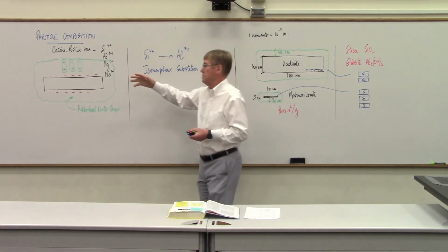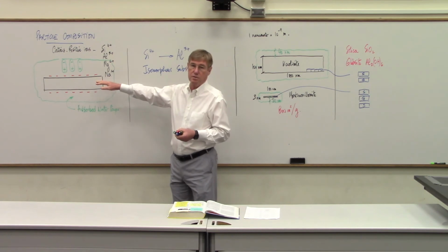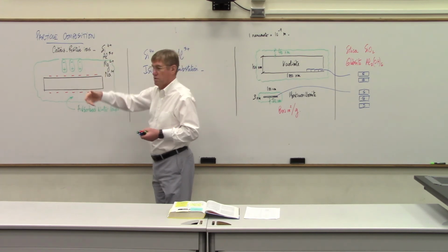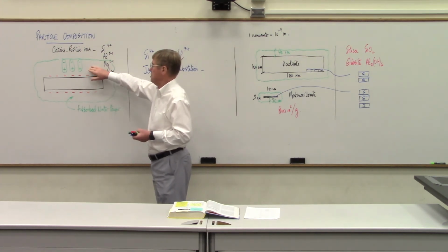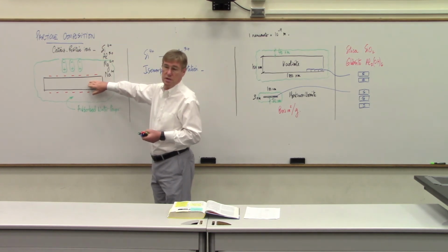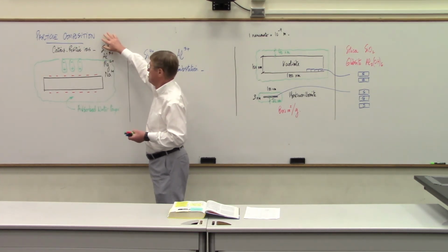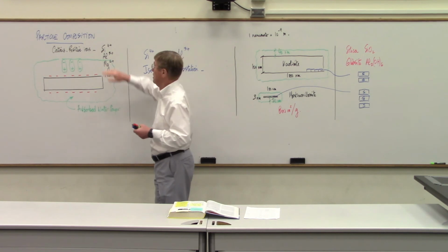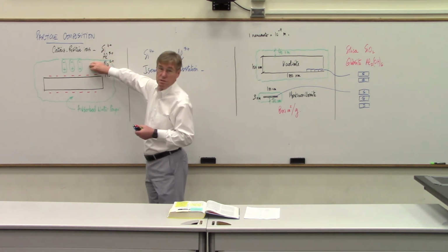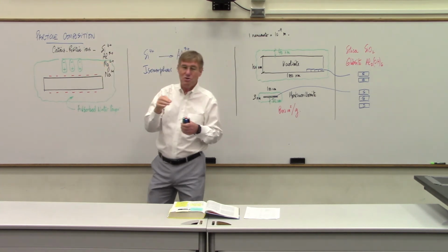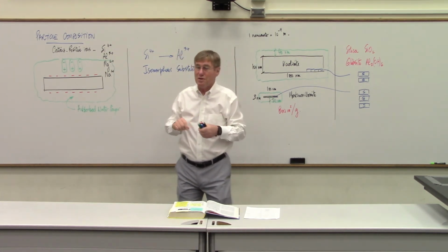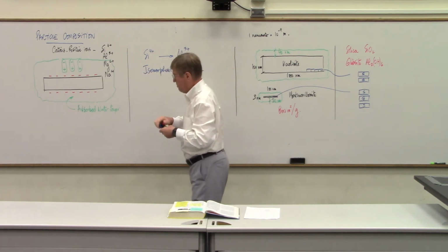And that's where the electrical part of these clay particles develops. And this water is not water when you open the tap. You know, this water is very strongly bound to the particle. As you get closer to the particle, the water goes from free water that can actually seep through the soil to this viscous water that's really attached. So if you had a knife that would be so small, in nanometers, it'd be tough to scrape the water off the particle because it's so strongly bound to it.